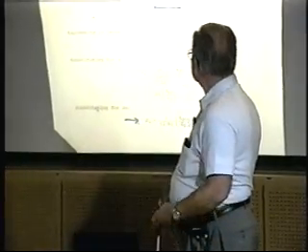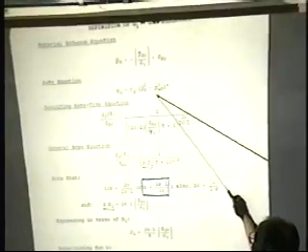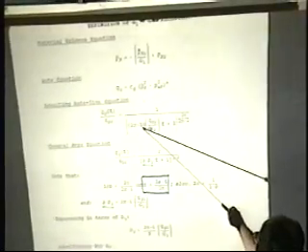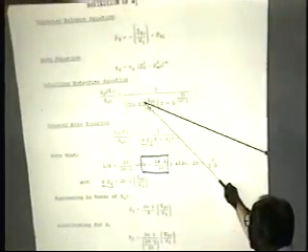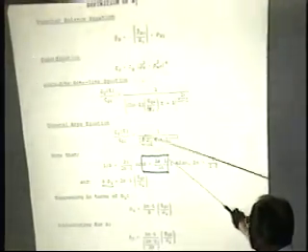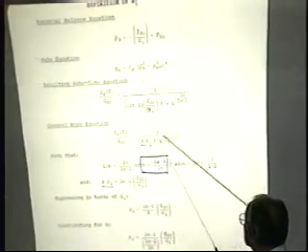I sort of preceded myself here, but here's what we did. We took the material balance and the back pressure equation, and that's how we got this equation here. Then we equate this rate time equation for gas wells to the ARPS equation, and I can define 1 over B is equal to this.